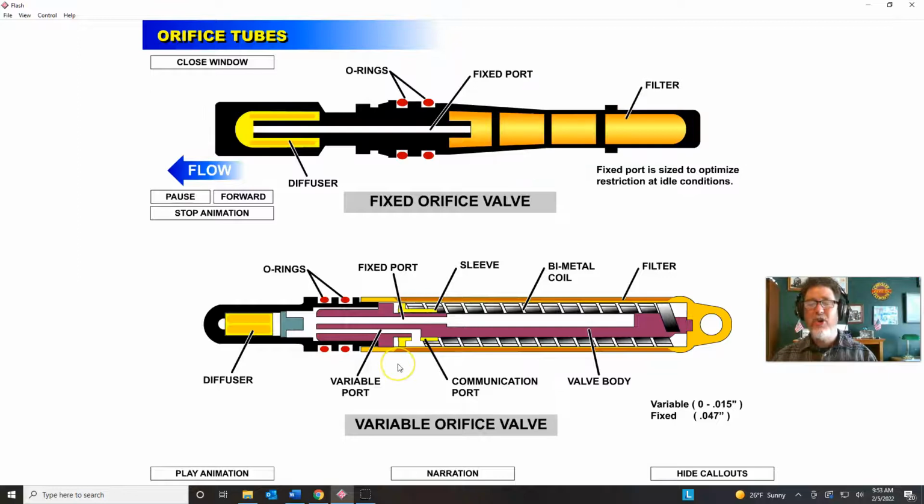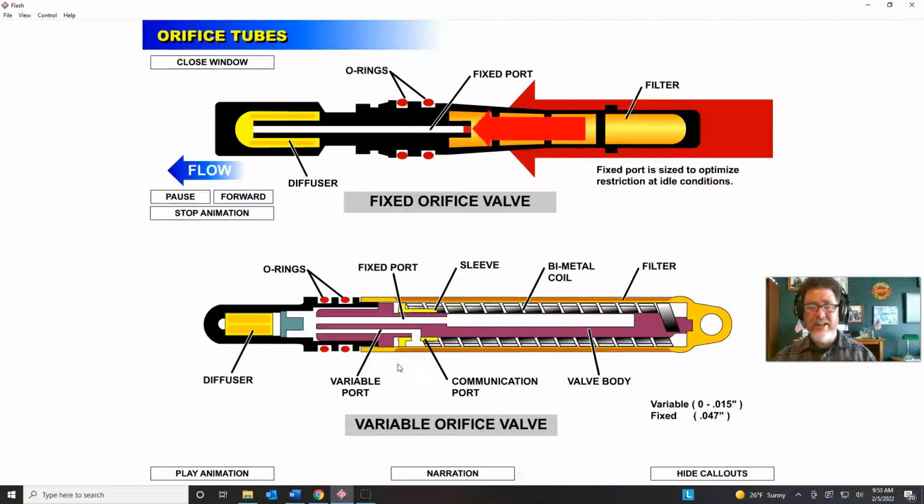So almost always, and the reason I ask this is that almost always students get it wrong. The reason they get it wrong is that they use their knowledge of a TXV system, and they say, wow, on a TXV system, if I have a high heat load, pressure goes up on the suction line, I want to open up the system. And when I don't have a high heat load, I close the system. So they use their knowledge of a TXV and apply it to a variable orifice valve. And they say, well, it works just the same. And no, it doesn't. It does not work the same. It works just the opposite of a TXV. So if you think about it working the opposite, that helps you remember what's going on.